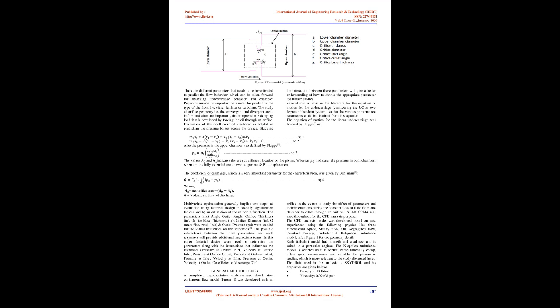The present work discusses the design of experiment, DOE, method used for arriving at the optimum number of simulations required to assess the interactions between the input parameters, which are critical to the performance of shock strut, and at the same time maintaining the accuracy required for assessing the influences of different parameters like orifice geometry, orifice inlet angle, orifice outlet angle, orifice thickness, orifice diameter, chamber geometry, diameter of the lower chamber, and diameter of the upper chamber. Refer Figure 1 for the geometry details, gas pressures, mass flow rate of oil through orifice, etc.